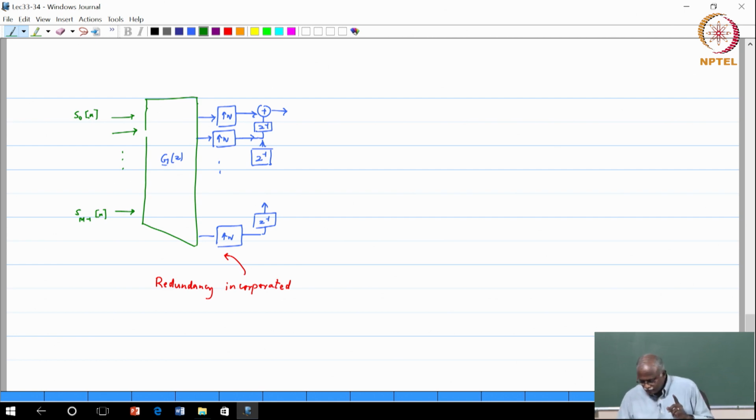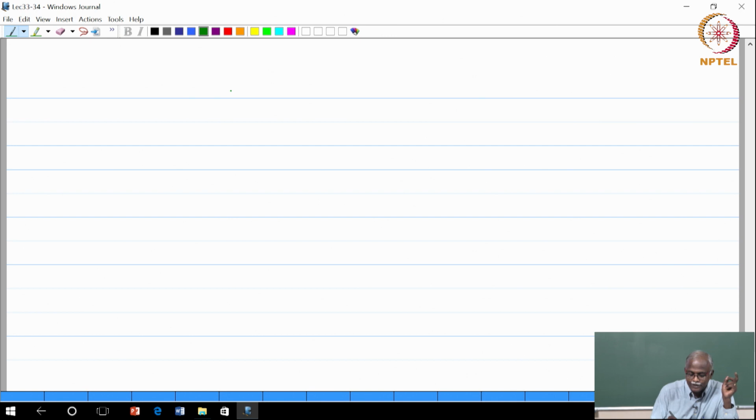So, now I want to move to the analysis filter bank. Okay, analysis filter bank is the one where we are going to split it back. If you remember, the analysis filter bank is where you do the serial to parallel conversion. There we wanted to have it as powers of z. So, here is the representation. I will just introduce it and then we will pick it up in a few minutes. So, if I denote the filters that I have in my analysis bank by H, here is a way to visualize it.